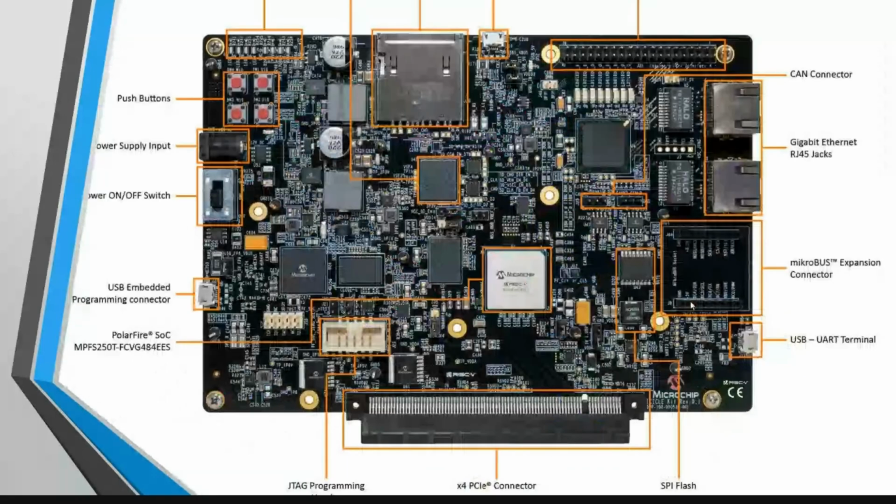So this is another board, as you can see. This is your RISC-V processor SoC, the polar SoC. Other than this, there are many analog components on the board, and there are some digital ICs, sensors. GPIO is a vector, where your primary input and output are, which will be connected to each and every component here.